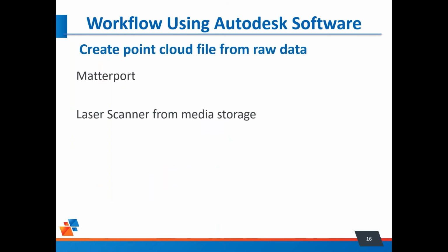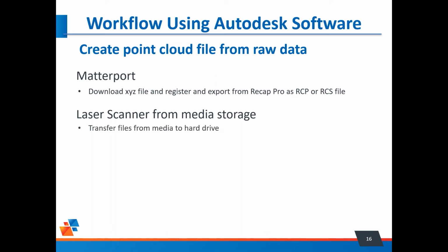So then we create the point cloud. We've already created the point cloud from the raw data, whether it's Matterport, where we download the XYZ file, register it, and export from Recap as an RCP or an RCS file, or just transfer the files from the laser scanner to our hard drive and use Recap to make the RCS file.